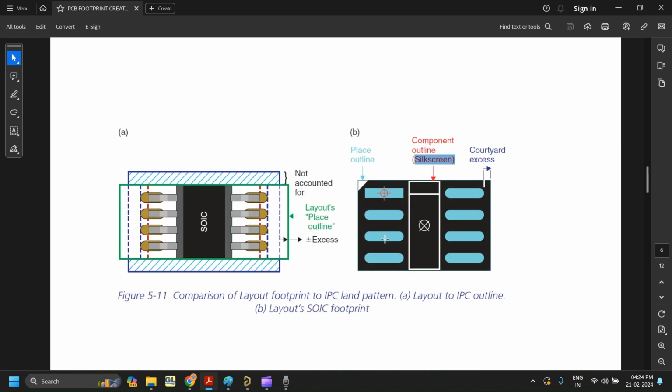And for the SMD components, this is the SOIC package, and if you are a beginner, you may be confused about what this SOIC is. So there are some naming representations for the footprints. For example, for the chip capacitor and resistor, there are size codes like 0603, 0805, 1206, 1210, etc. The size increases as the component size increases. And similarly for the SMD components, there are different types of packages like SOIC, TO263. So you have to understand that SOIC is the case code.